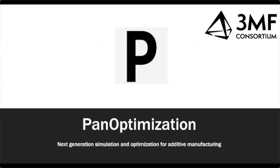The issue that we're facing is that Intel has a bug in the MKL distributed version, the MPI version. When the number of non-zeros in the matrix gets close to the 32-bit limit, 2.1 something billion equations, no, I'm sorry, non-zeros, the solver crashes. I reported this to Intel about a year ago, and they promised they're going to have a fix for this in the 23.1 version, but they've been silent lately, so I doubt that's going to happen. So if you've got anybody at Intel, let them know.